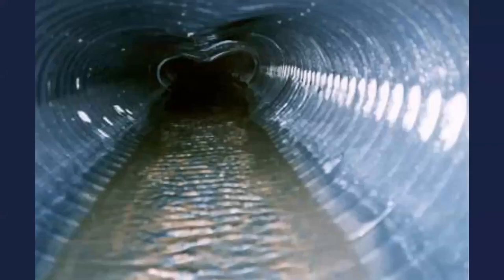Okay. This picture shows some buckling on the top where it's been overloaded. It's not just an obstruction coming through the pipe. This one is actually, over time, it's been loaded too much. You could see on the right-hand side, there's kind of that whitish film on the side. That is actually from crazing. Over time, as that plastic bends, it's going to become weaker and weaker, and it's ultimately going to collapse. So that's an issue as well.